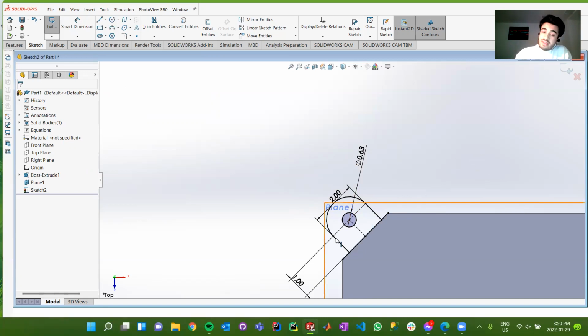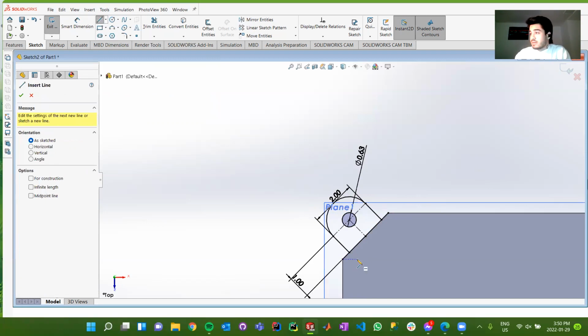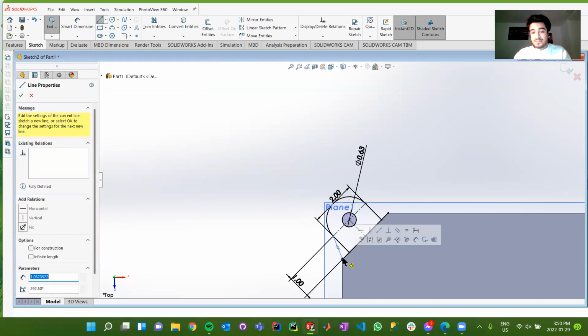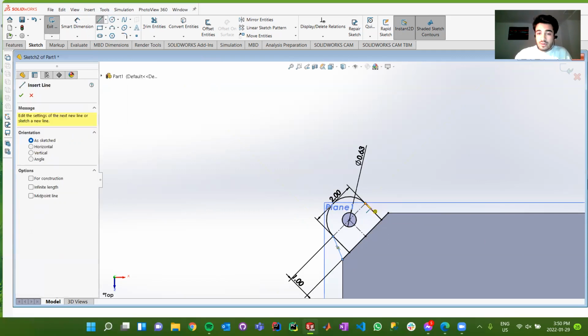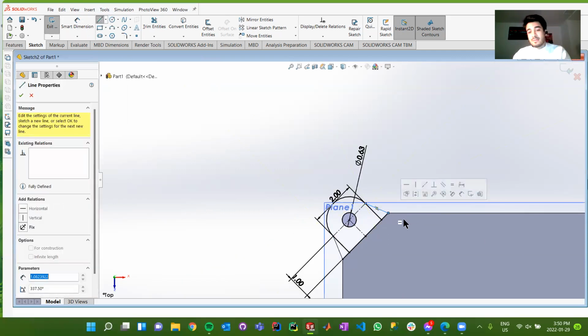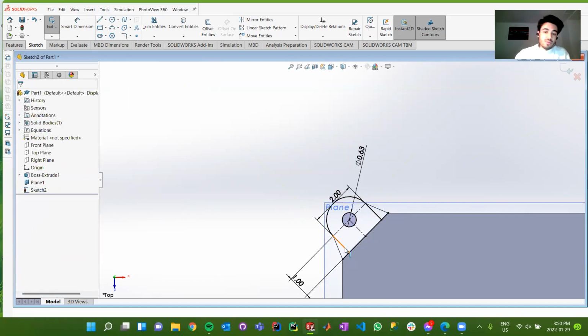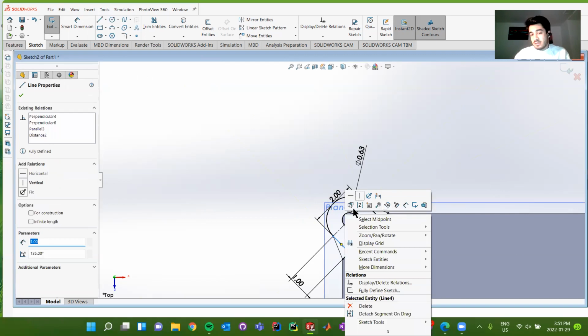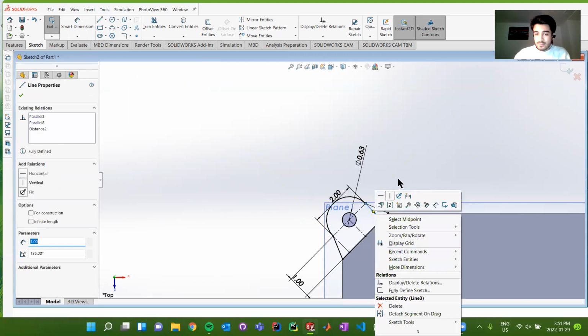And then we can taper this off such that we don't have this stress concentration right here by essentially drawing just another baseline. So it doesn't really matter where we put it. In the CAD, I sort of put it in an arbitrary location, but I can change that as well. I'll just have it such that it goes from here. Now that we have an actually solid idea of what our CAD is supposed to look like. And such that we don't have to actually remove these lines, you could make them into construction geometry. So that's what I'm going to do.